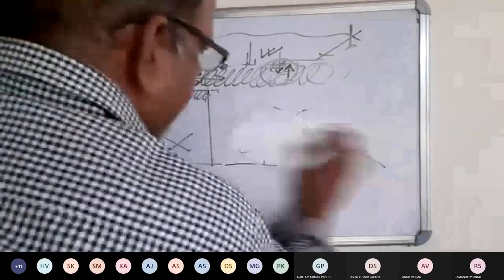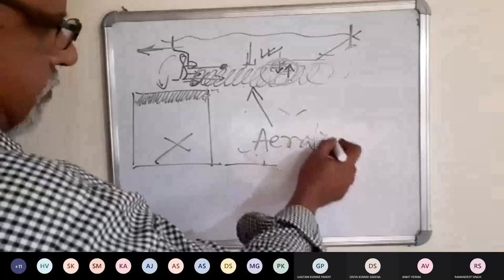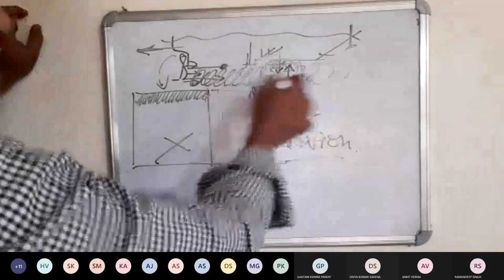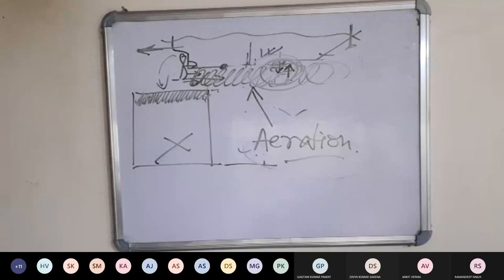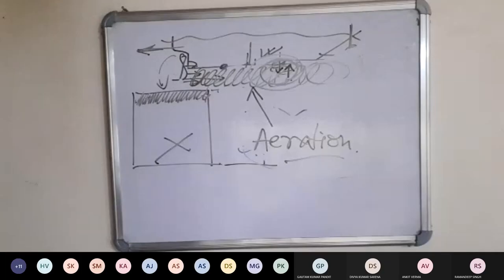This particular problem is called aeration. Bubbles stopping or obstructing the signals is called aeration. Cross noise is that the receiver is picking up the signals directly, not reflected, but directly coming from the transmitting transducer, causing a dark mark near the zero line. But of course, the swept gain control takes care of that and it reduces the error, or rather cross noise.